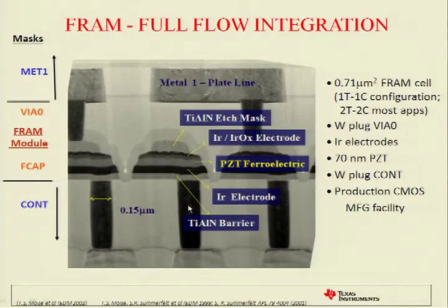Okay? So let me talk about this in just a little more detail. Here's a picture if we blow up those capacitors, expand it a little bit, of the actual materials involved. So the key is this PZT ferroelectric here. This stands for lead zirconate titanate. It's about 700 angstroms thick, and it's deposited on an iridium electrode. And iridium is a very expensive material. Why in the world would we use iridium?